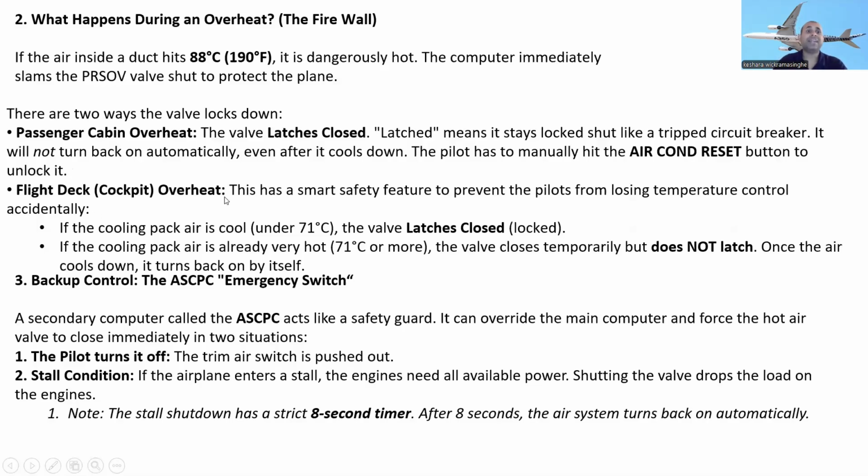Remember, the flight deck cockpit overheat has a smart safety feature to prevent the pilots from losing temperature control accidentally. If the cooling pack air is cool, under 71 Celsius, the valve latches closed, locked. If the cooling pack air is already very hot, 71 Celsius or more, the valve closes temporarily but does not latch. Once the air cools down, it turns back on itself. Okay.